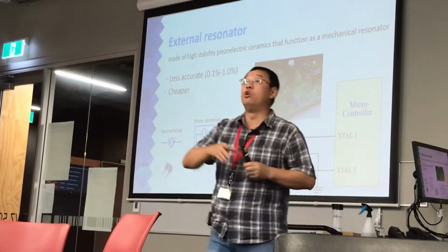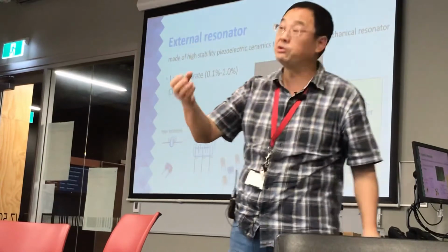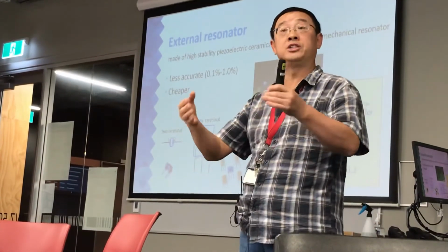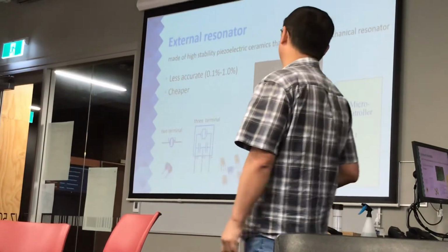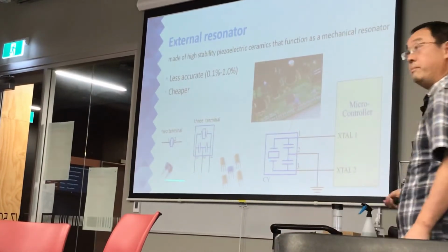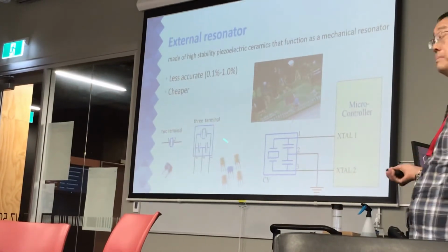Otherwise, the ADC will be fitting noise; you cannot tell whether your sample is the noise or the real sample. So that is very important. You've got to remember this when you design the microcontroller.